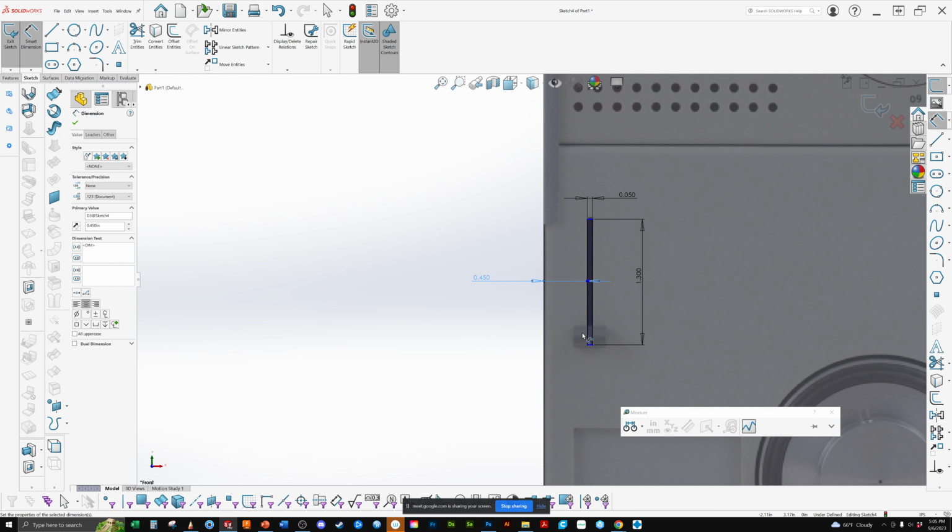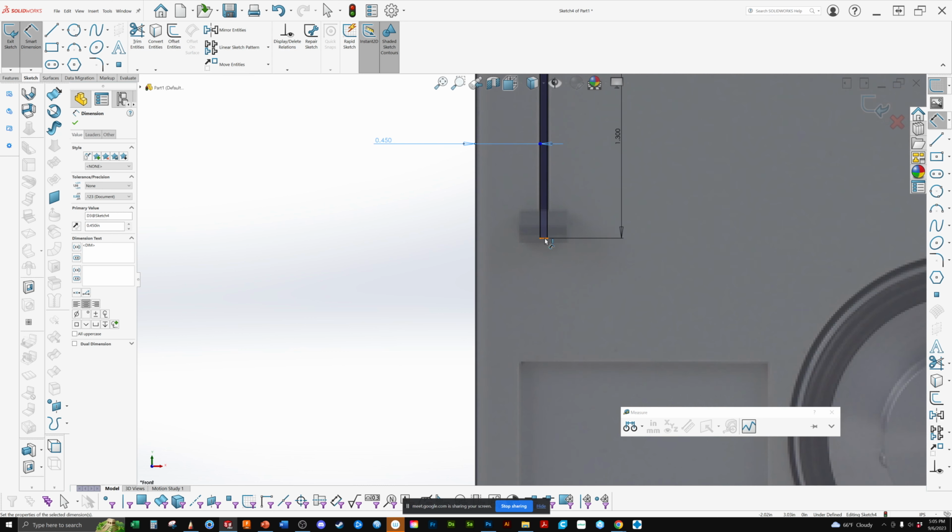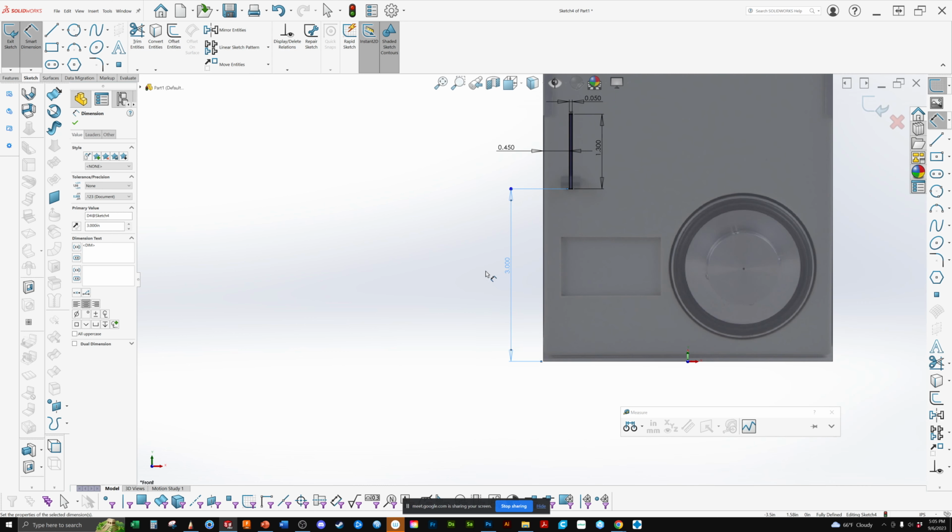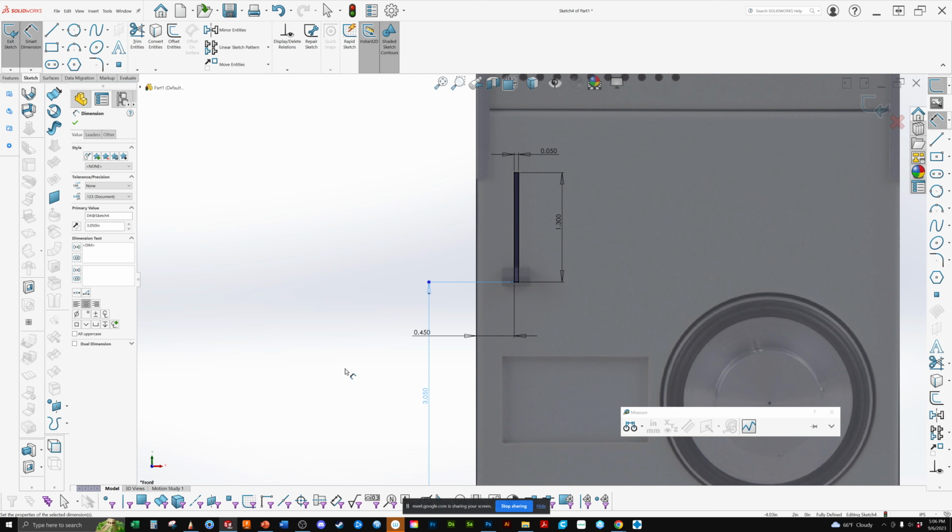I would probably even want to lock it or dimension it all the way to the bottom. And you can see that they've got pretty clean numbers. So it's 3 inches from the bottom. The 0.02 was me just drawing it in a little bit. Oh, it went the wrong way. So actually it's probably 3.05. And then I can do my first cut.